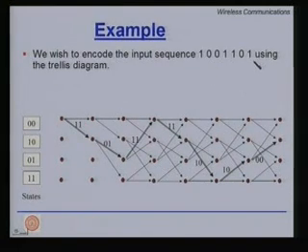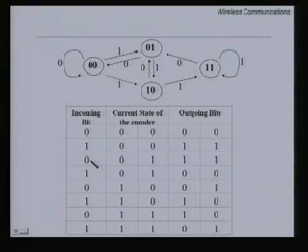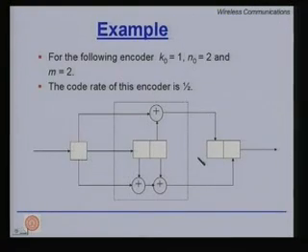Question? Sir, in the previous diagram, can we change the logic? Okay, internal logic. Yes. So, the question being asked is, for any trellis, this trellis or the previous trellis, can we change this logic? So, the answer is yes. In fact, that decides what is a good encoder and not so good encoder. In fact, what is written out on the branches, what is output, depends upon what is the logic we use.